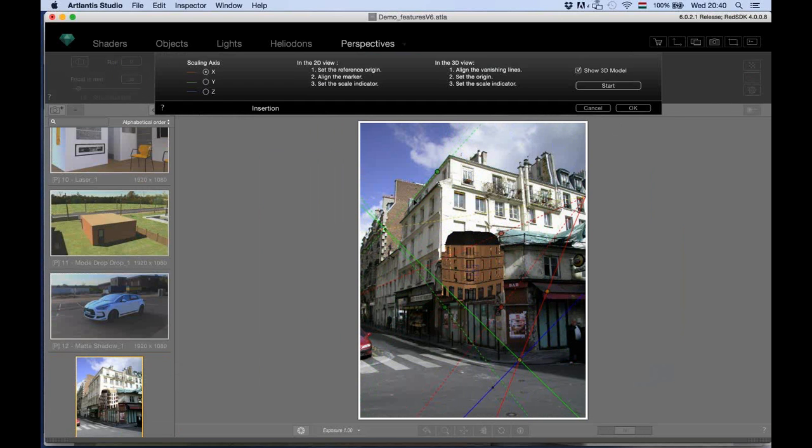I'm not setting the axis, I'm setting guidelines for the axis this time. These dashed lines can be grabbed anywhere on the surface of the image, and that makes it very easy to detect the best positions where I can easily find the directions toward the vanishing points. So let me drag for the x-axis. I'm just using, for example, this walkway. Here it is. Good. A little bit like this.